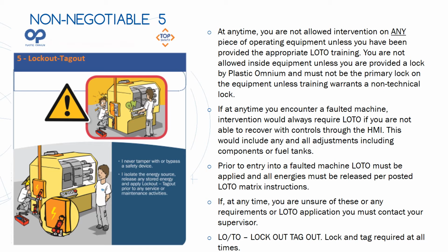Prior to entry into a faulted machine, lockout-tagout must be applied and all energies must be released per posted lockout-tagout matrix instructions. If, at any time, you are unsure of these or any requirements or lockout-tagout application, you must contact your supervisor. Lockout-tagout, lock, and tag are required at all times.